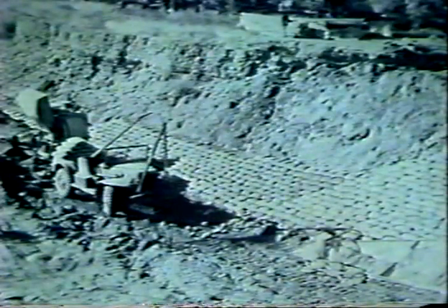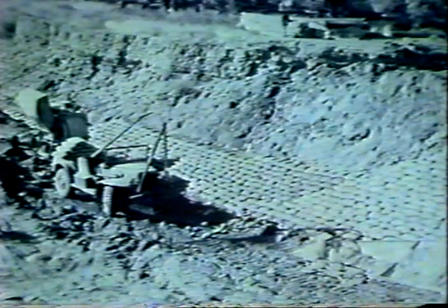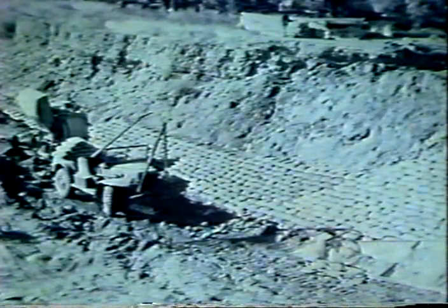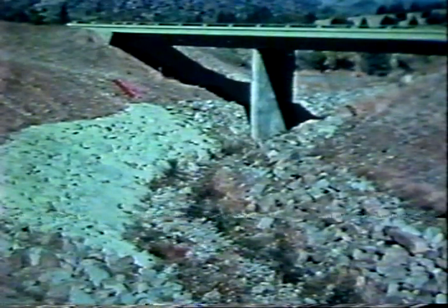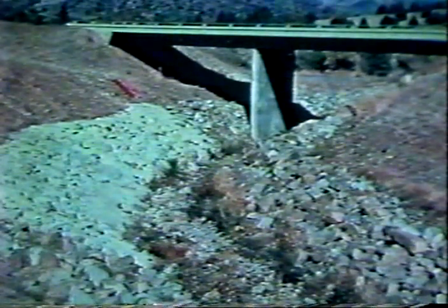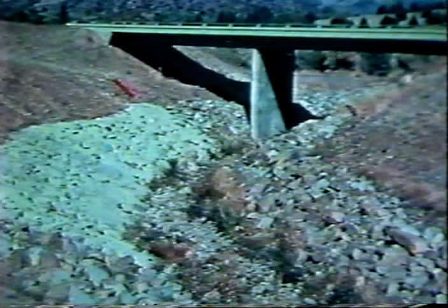In places where rock riprap is not readily available, sacked concrete revetment is sometimes used. It has the advantage of neat appearance, but like other rigid revetment, is subject to progressive damage by undermining. Sacked concrete installed in 1956 at this bridge site in Nevada has proved to be effective. Concrete grouted riprap, shown here between the red markers, has been used effectively as bank protection on many mountain streams in California. But penetration of the grout into the rock interstices is essential for good performance.